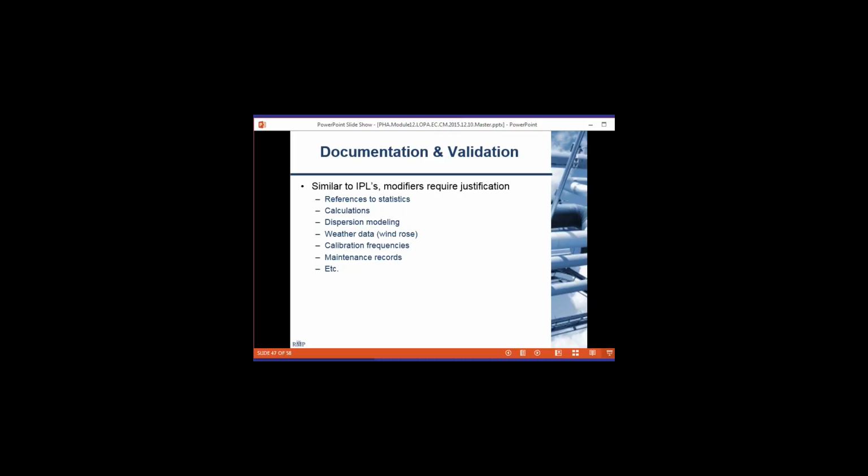At the end of the day, you're producing a document that is justifying the safe posture at your facility. You need to justify everything you do in order to make the team agree and say, you know what, this is true. This is a true enabling event. This is a true conditional modifier, and we feel comfortable adjusting our LOPA data based on these events.